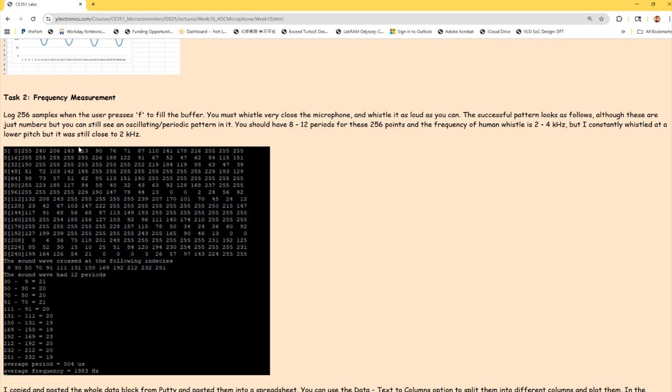All right. So let's start with question number 1 first. If I define in the code the sample period, right? Just do a define sample period to be 25. Remember the sampling rate: I'm taking every 25 microseconds to sample 1 point. But as a variable, as a constant, it's very difficult to put a 25 times 10 to the negative 6 over there, right? So what we usually do is I define that period to be 25, which is actually 1,000,000 times larger than what it should be, and the unit is microseconds, right?